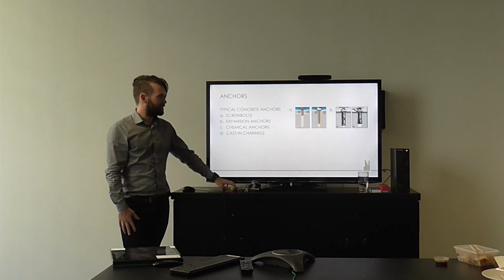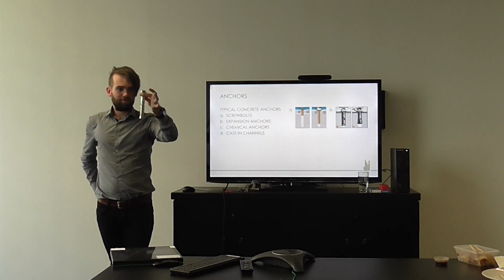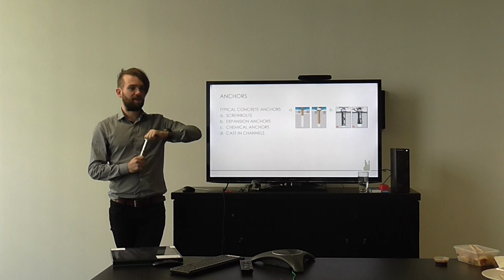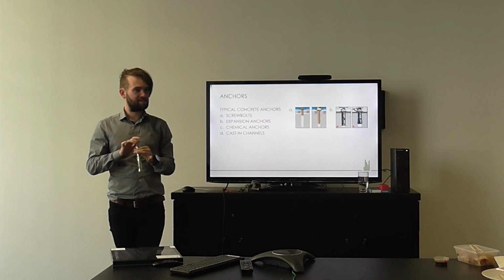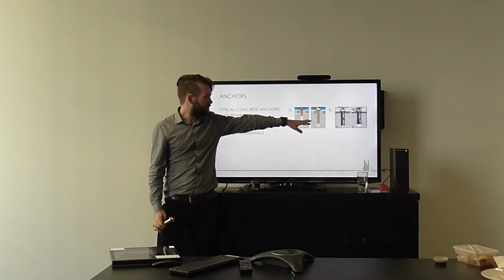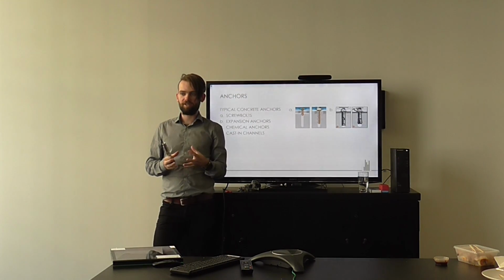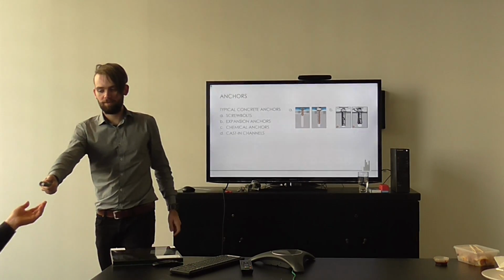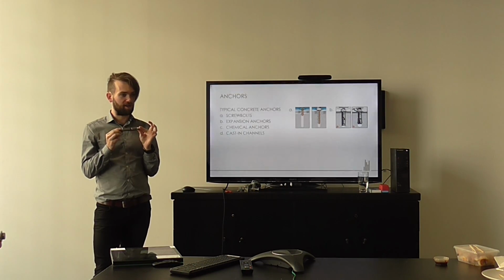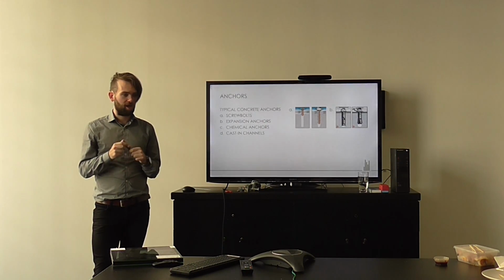And then the second one we've got here is what's called an expansion anchor. So it looks like this big fella here. Now, what they do with these essentially is they will bang these into the hole. They come without the nut on top of them, but they bang these into the hole, and essentially they will then torque these up, and as they're torqued up, you can see here that the end of this splays out. Now what that does is it causes friction in the hole and holds the anchor in the hole. There are two types of those. This is a little more fancy one, so it's called an undercut anchor, where the splaying out mechanism is a bit more heavy duty, about $100 more heavy duty.